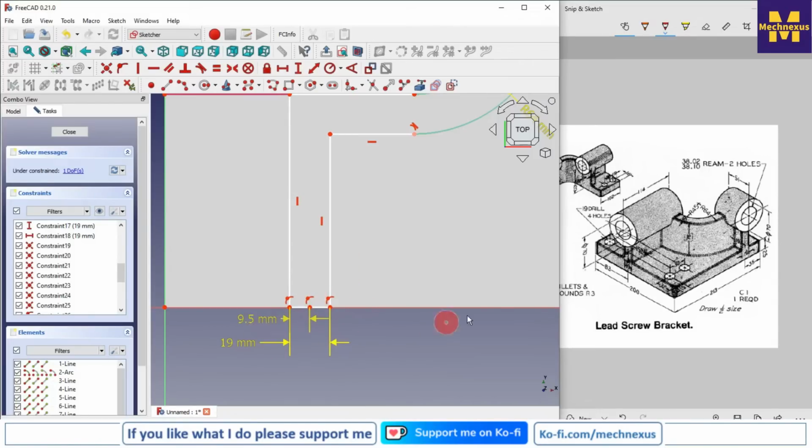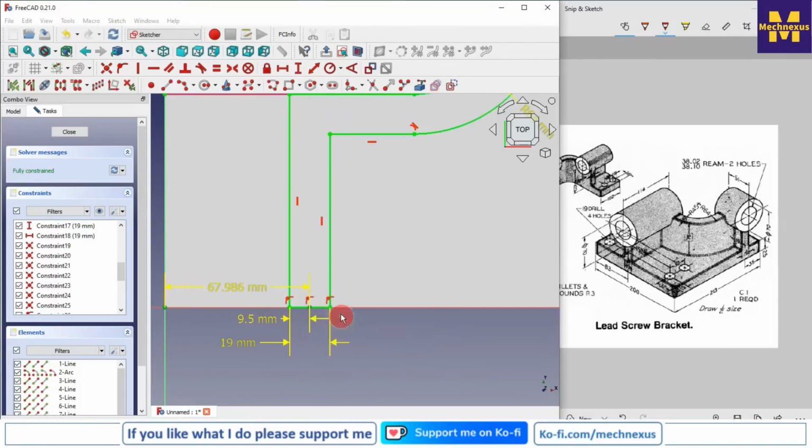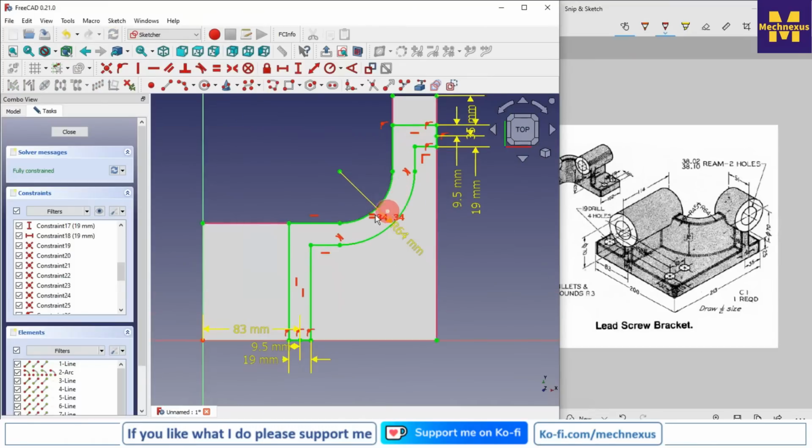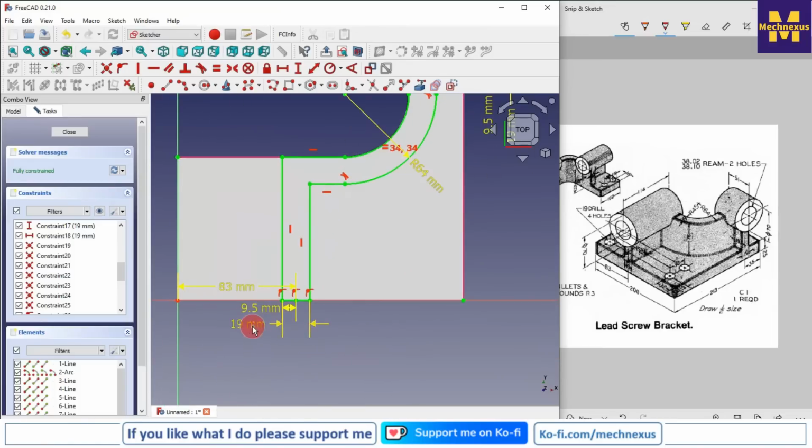I move it, and now we can see that here is a dimension 83. So now I will select the horizontal dimension, select these 2 points and give 83 dimensions. So you can see that we have fully constrained our sketch, and let me move the dimensions so that you can clearly see it.